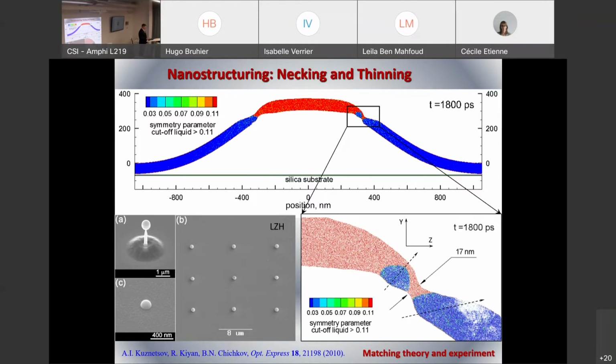So this also happens in this experiment, as you can see, and if we apply a little bit higher fluence, this droplet can fly away and even be caught by a receiver glass that we can put at the top of the structured surface. So eventually we can see that we basically reproduce the experiment, and also noticeably that we have formation of nuclei of a new solid phase just inside the liquid, which means that the temperature of this liquid is much below the equilibrium melting temperature, because the nucleation barrier was overcome.